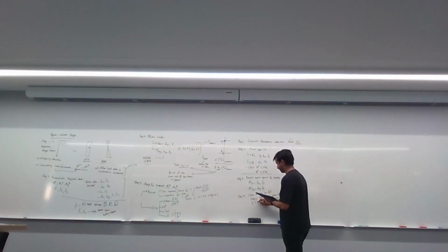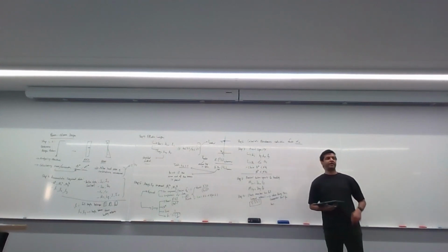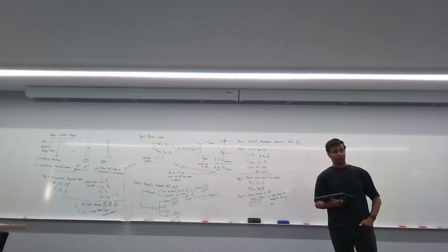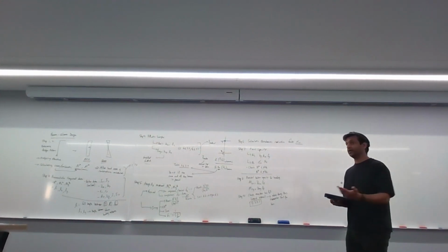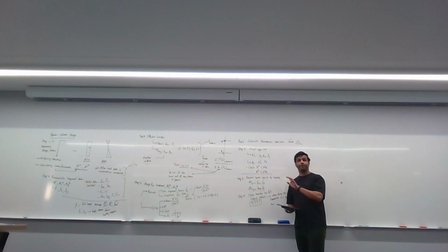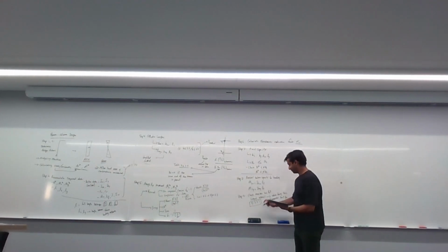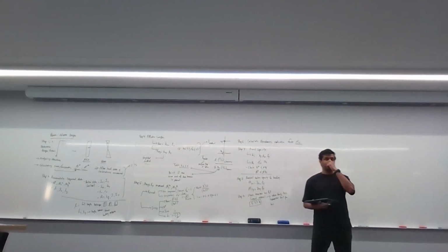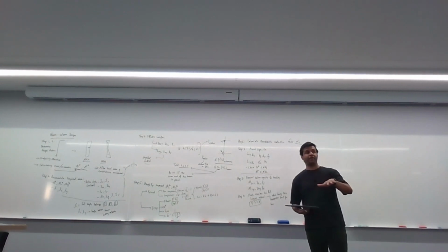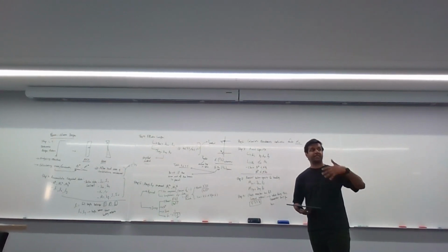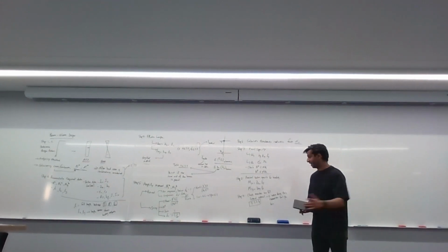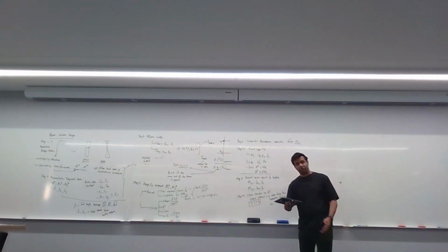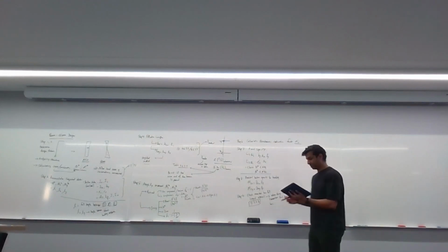Yep. Check whether a member has full lateral restraint or not. Use clause 5.3.2.4, sorry, those formulas to figure out if it is in fact continuously laterally restrained. If it is, the point is your governing capacity is MS. If it's not continuously laterally restrained, meaning it fails the formulas here, then you've got to continue with the working to calculate what MB is.